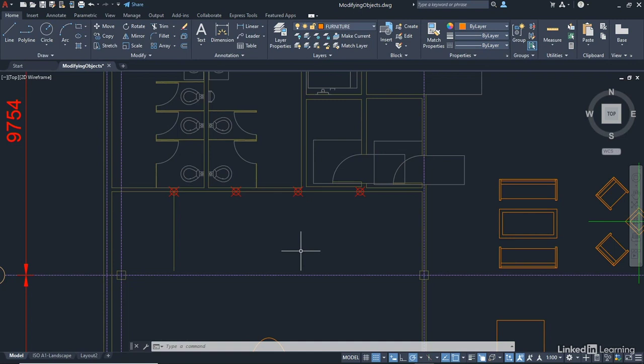Now, we're going to take a look at how we select objects in our AutoCAD drawings. The quickest and easiest way is to move the crosshair over an object, that line there. You can see it highlight. If I get the pick box over the line and left click, that will select that line. And you can see it's selected. It goes a pale blue color, and the grips that are relative to that line's geometry are there as well. So a line has 3 grips. It has one at each end and one on its midpoint, as you can see.